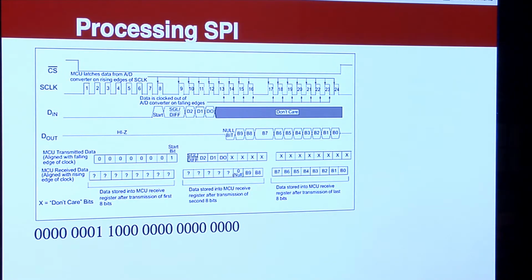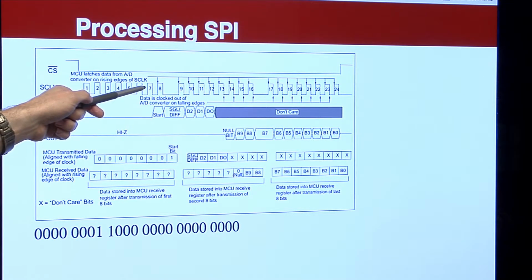If you have a string of zeros, won't you have a clock slip eventually? Not sure what you mean. So for the Raspberry Pi to read in the bits that come from the A2D converter, it's going to have to read them in sequence at the right timing. The A2D converter is sending it, but it's determining the timing, because it's what's pulsing the clock.